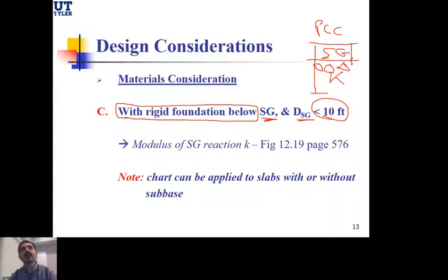I need actually to take advantage of this, because now having a strong subgrade with a bedrock very close to the surface, that actually will influence eventually the thickness of the PCC layer. Instead of, let's say, needing 6 inches, I may need only 4 or 4.5. So this correction, you'll see, is gonna pump up the K value that we got from the first step. And I'll show you in a little bit here what I mean by this.